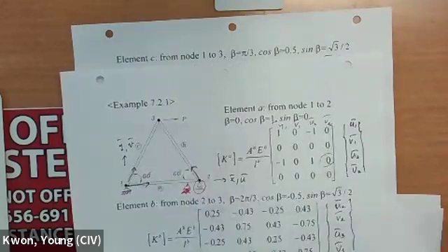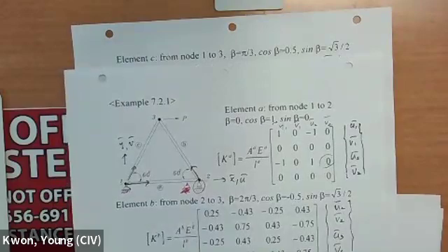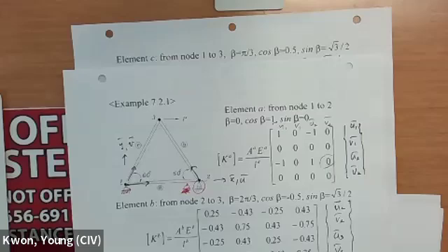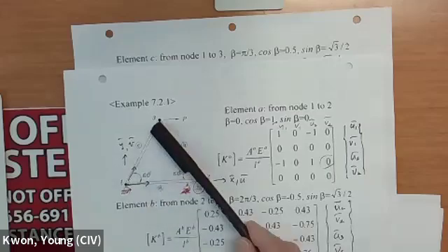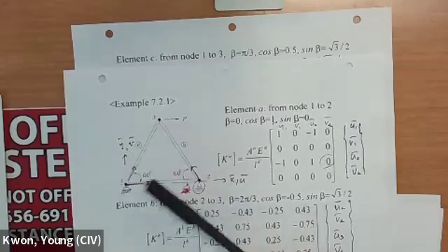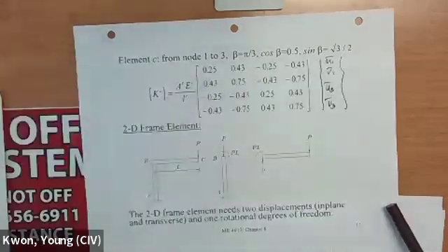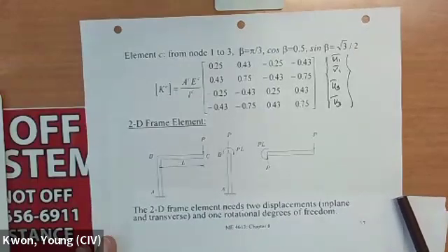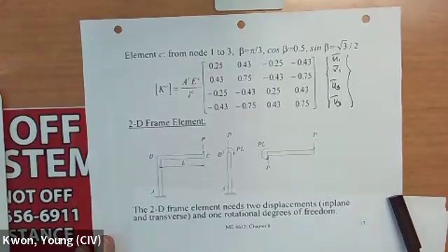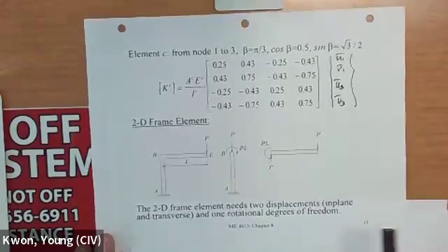We can find all those displacements. If you do this with just statics, from the method of joints and method of sections, then you only get the reaction forces at the joints, but not the actual displacements. So this has the advantage of giving both pieces of information. That's what we talked about last Thursday.